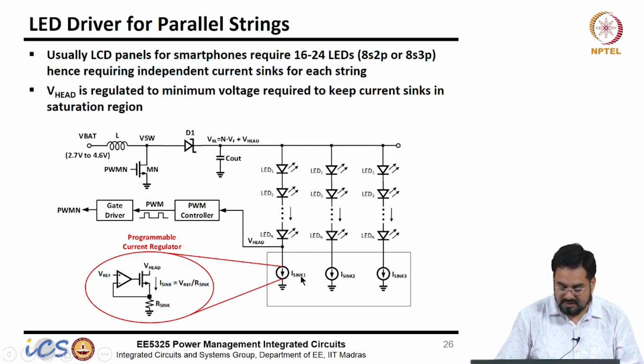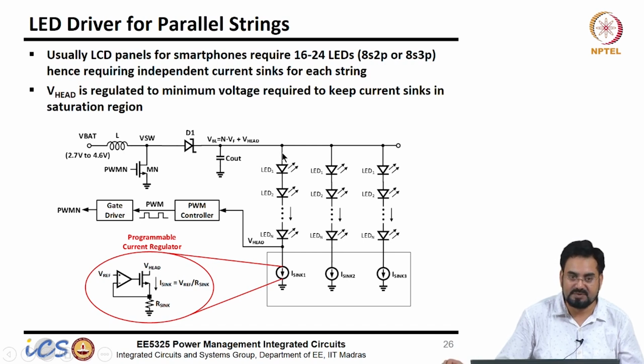The main reason we do not want to put it here is that, as I mentioned, we do not have a high voltage PMOS here, and if you are putting it here, then you require a high side PMOS.